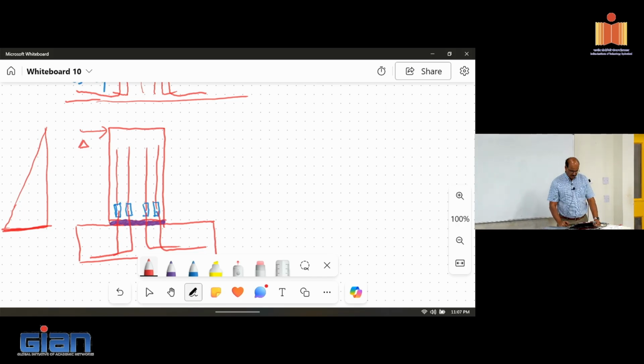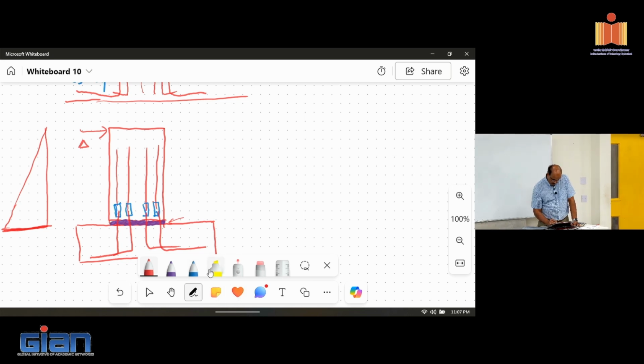There are a few things to observe. It depends on what you use as a grout. So if you use regular grout, fiber reinforced grout, UHPC, those things would play in whether the crack develops within the grout element or within the concrete element. There's a natural interface here which has almost no strength. So this location, let me see if I can find, somewhere here it could be at this location.